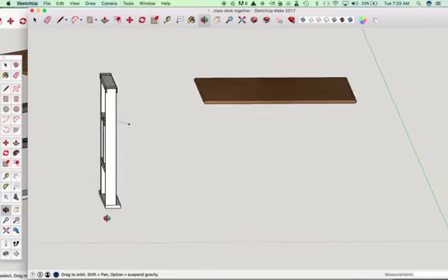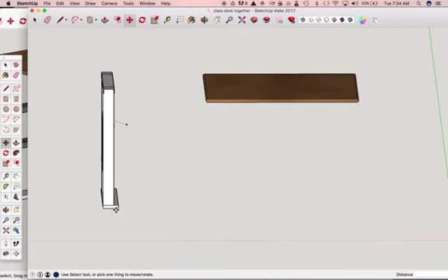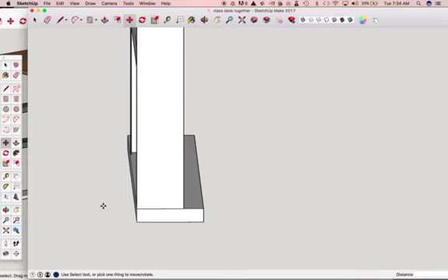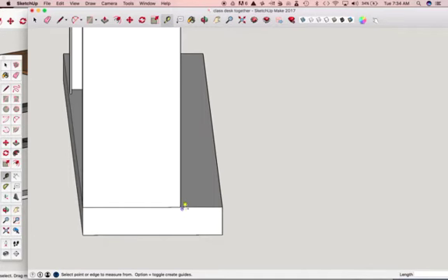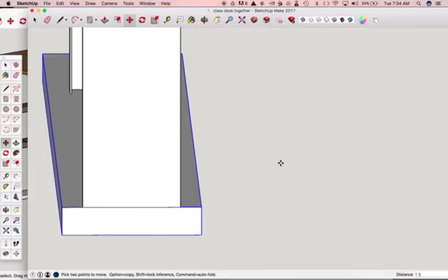I can see that's not centered very well, so I want this to kind of be in the middle. So I could either eyeball it or I can do the math. I always prefer that you do the math. So we need to make this distance here be the same as the distance here. So the way I'm going to do that is I'm just going to measure from here to here. I see that's 3. 3 divided by 2 would be 1.5. So that means I need to move this guy 1.5 this way. So let's do that. Type in 1.5, and we're done.